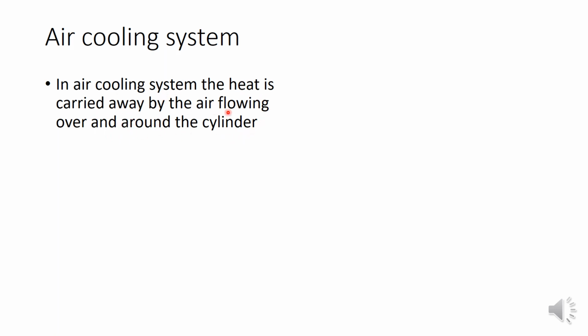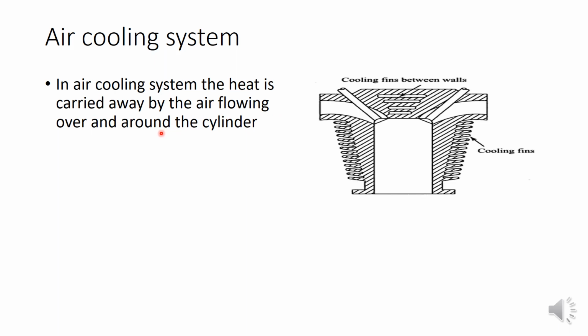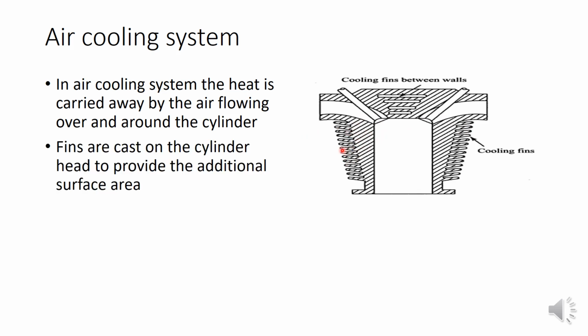So in air cooling system, the heat is carried by the air. So no water or liquid is used here. And mainly we can identify that it is applied in bike, smaller engines like motorbikes. We can see a number of fins. In air cooling system, these fins are very much necessary.